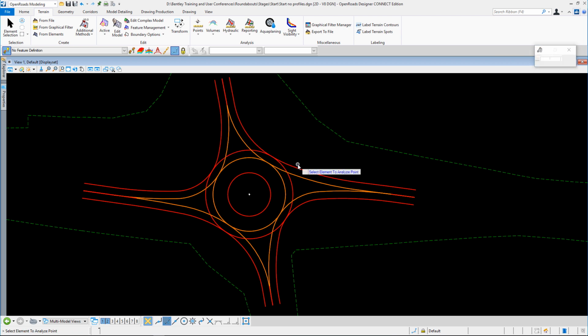So everything's going in the correct direction, and that's the kind of work you need to put in to start with. Because these are single carriageway, these are going to be coincident at the beginnings and coincident at the ends. So that's where we want to be. Good time spent at this point is good time, and we'll end up with a good three-dimensional model, which we can then use to do isopacks and testing to see if the roundabout's going to work. So that's pretty much it for this stage. There'll be a series of videos to follow that take you right the way through the process.